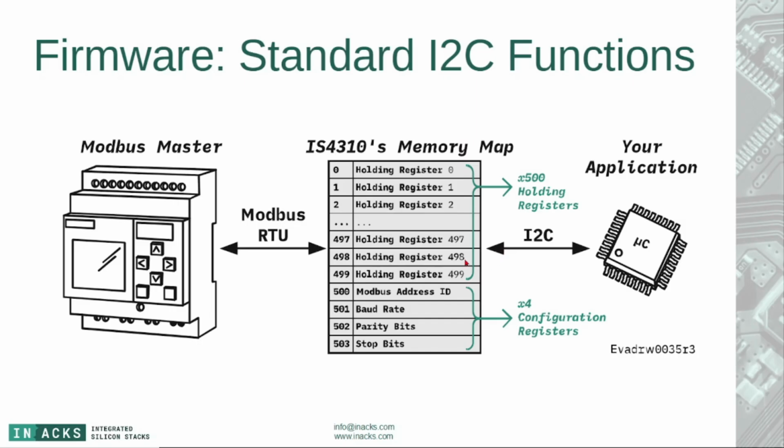Now, on the firmware side, how do you interface your microcontroller, your application, with the IS4310 Modbus chip? And how does the chip interface with the Modbus Master? So think about the IS4310 as a memory chip, as a typical I2C memory chip. You actually have 500 holding registers.